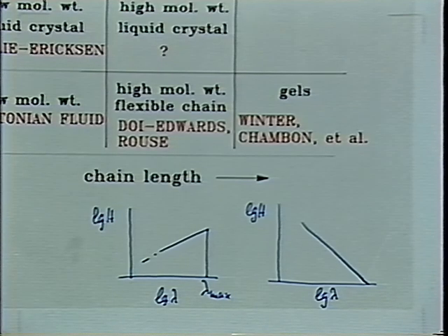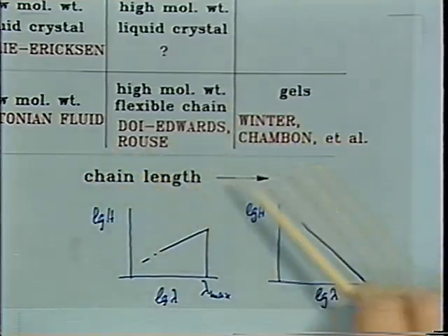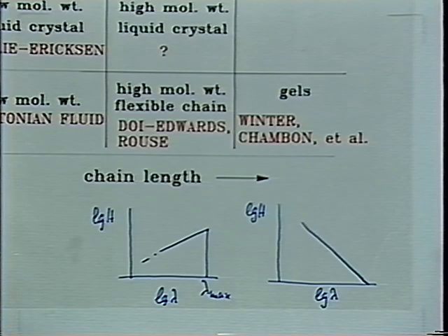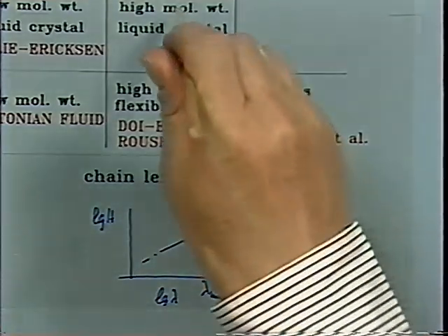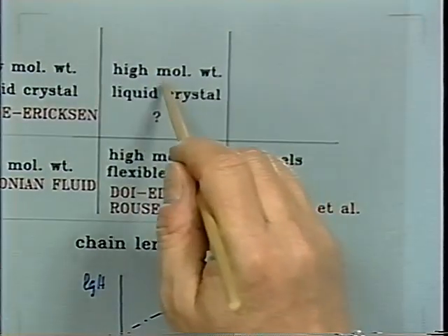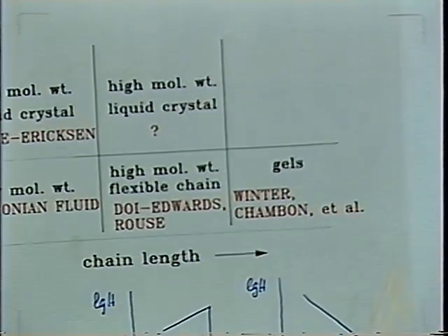If the molecular weight distribution is broadened, say, by the chemical reaction when making long molecules, you most likely have a broader distribution. And in the extreme, you see that in a gelation process where you go from a liquid to a solid in a cross-linking reaction. And at the gel point, again, we would know the spectrum. So there's some information available for flexible chains at different status of their molecular structure. But if we want to know the behavior of the liquid crystal polymer, which has high molecular weight and chain stiffness, then very little information is available.